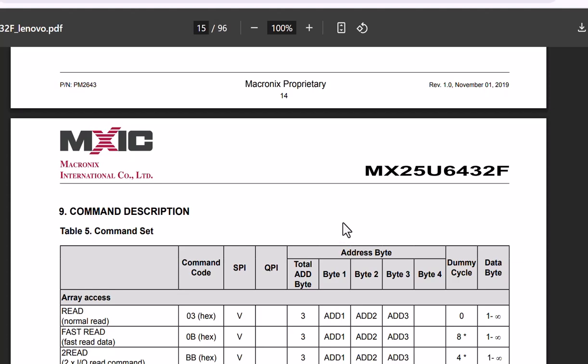A model is nothing but some RTL code which emulates that QSPI flash chip, so that you can have the simulation check with the timing. This model also has some timing parameters, so we can have the exact replica of that particular chip, so we can test on a simulation basis, so that we can verify our RTL code.